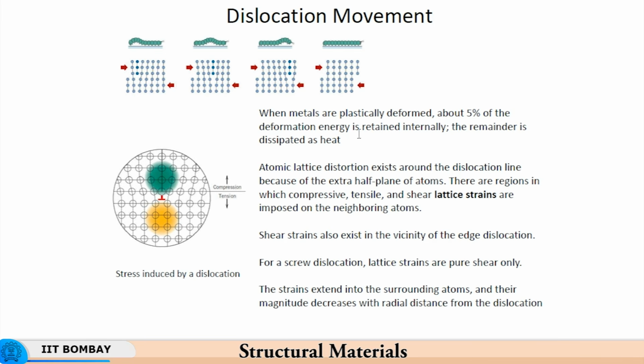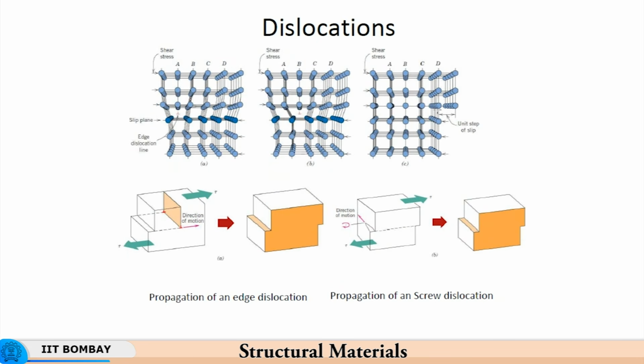So basically it's the movement of dislocations that results in a permanent deformation or a permanent change in shape, because now after removing the load, this structure does not go back to that structure. So once the dislocation has moved here, if you remove the load now, it is not going to come back to this. So in elastic deformation, yes, but this is therefore permanent deformation. So this dislocation which has come to the surface has permanently come to the surface. It is not that after removing the load it will go back and the surface will become as smooth and as polished as before. So that is the difference between elastic and plastic or permanent deformation.